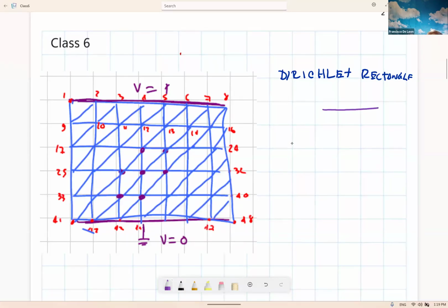So I have a rectangle that is formed by 4 conductors. The first 3 conductors are grounded. They are touching and grounded. And the last conductor has a voltage source applied to it. So it also goes to ground. Let me even remove this ground. Everything is there. So what you have is an applied voltage at the top and everything else is 0.